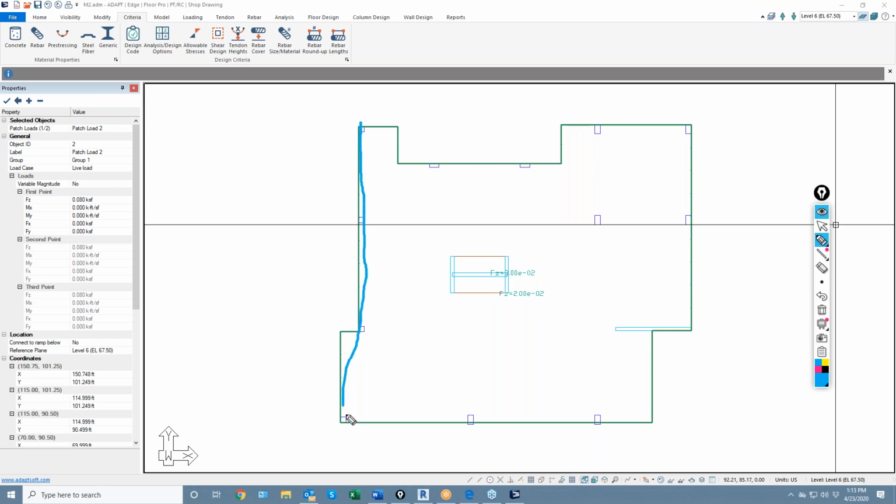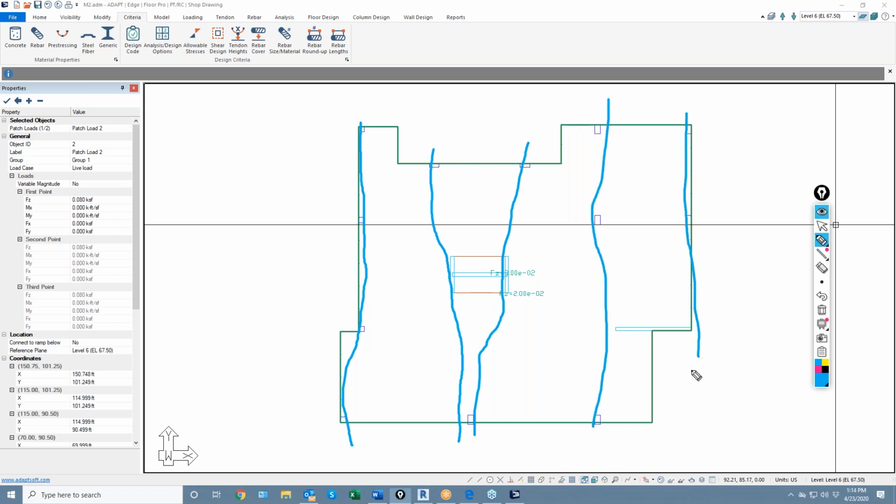So we're going to have tendons that do something like this. This tendon, I'm going to say, will just split. We'll have a tendon here and a banded tendon here. And then I'll represent the distributed tendons in pink. Now, again, if I wanted to represent the distributed tendons as bands, then I might say there's a bundle here, and there's going to be a bundle along here. Remember, the blue tendons are banded, so they're really like virtual beams in the slab that carry the distributed tendons. I might have another distributed cable here.